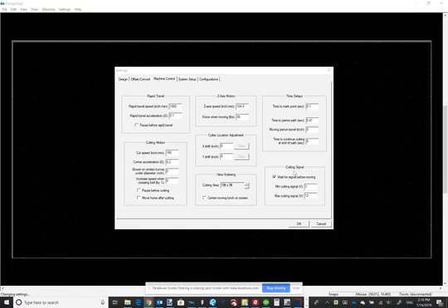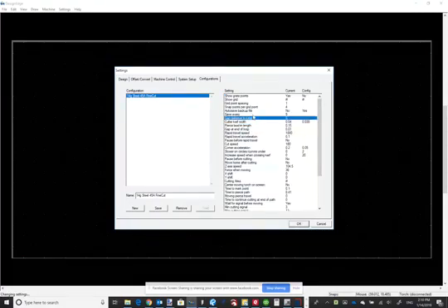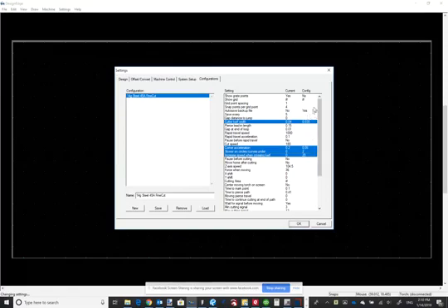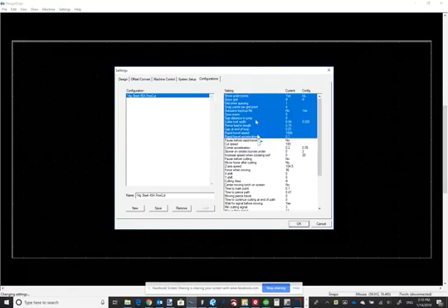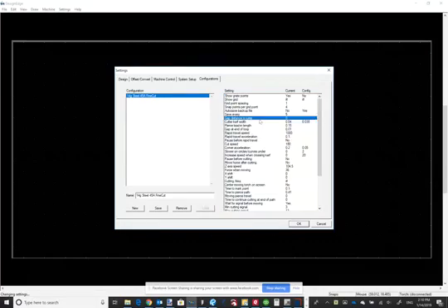And you'll notice it did one other thing when I added the advanced machine control: I get a whole new tab up here called configurations. This is where you can save your settings as different named files, and you can load them, either all or some. If I just wanted to load one or two things, I could hold control and pick the things that I wanted to load, and it would ignore the others. Or I can just click and drag and select them all, or pick a little section that way. That way you can load part of a configuration if you don't want to load everything.